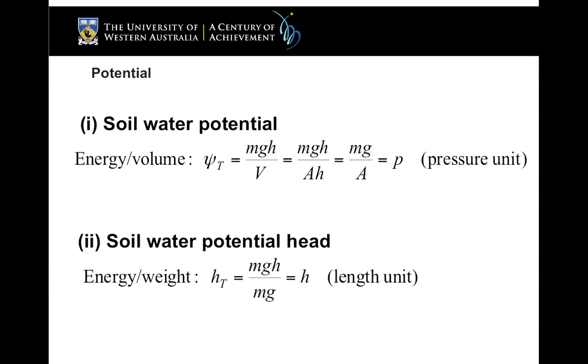So for example, you might see matrix potential has units, and you would have seen it if you attended the computer labs and looked at the first tutorial. The matrix potential of some of those soil waters were in kilopascals, a pressure unit, but you had to convert between kilopascals and centimeters of water. And so by doing that conversion, you can convert from a pressure unit, kilopascals, to centimeters of water, which is a length unit.